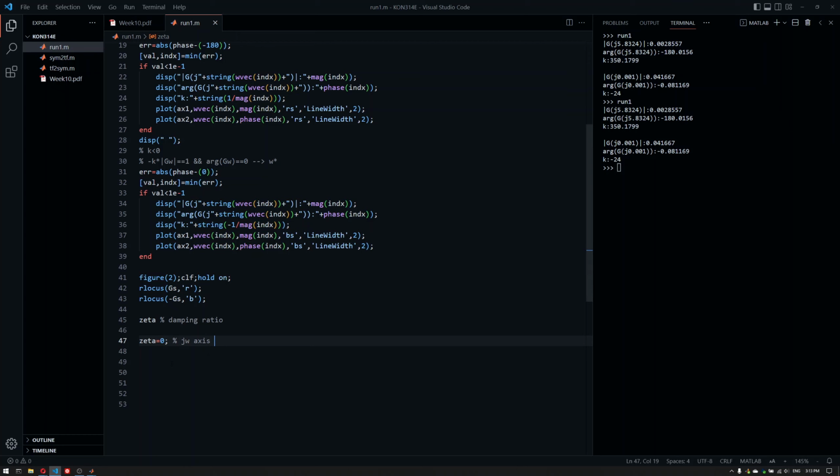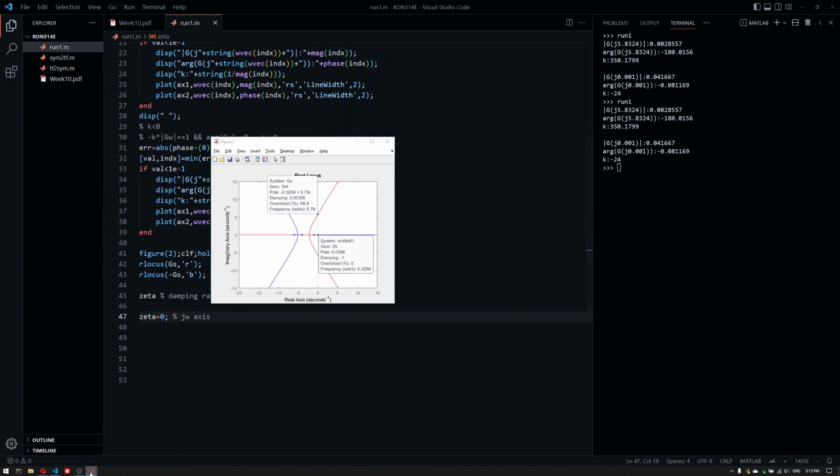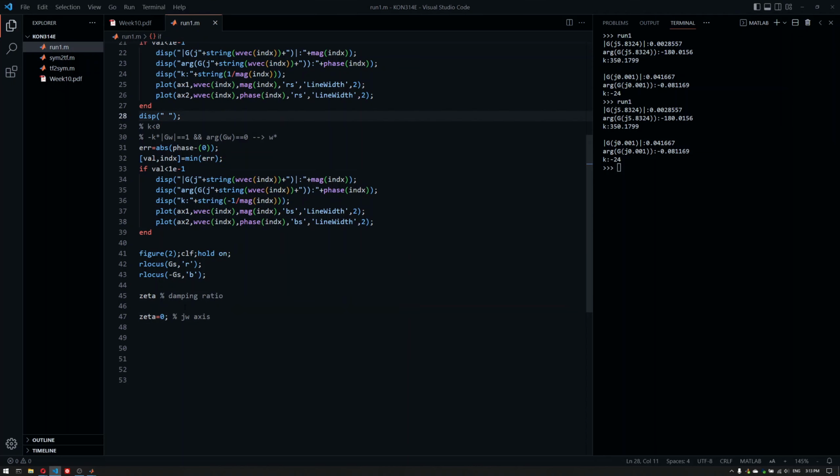So what I'm trying to come at is the following. We are going to use the distance from this stability bound or this margin in order to match that with a certain zeta value or a certain damping ratio of the system. And then that would correspond to a certain overshoot. So when we are looking for overshoot equals 10%, this will translate into a certain margin or distance from the phase, which is minus 180 degrees here.